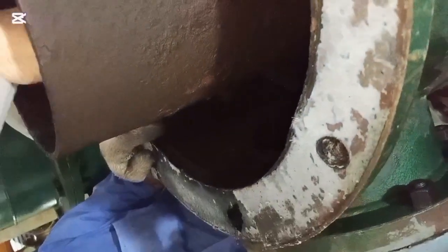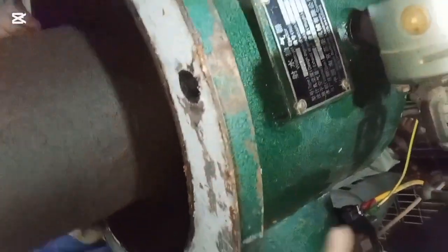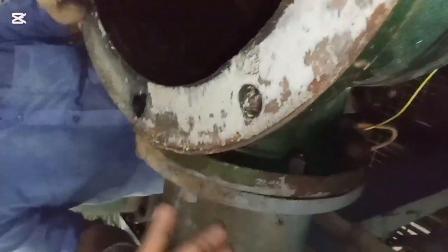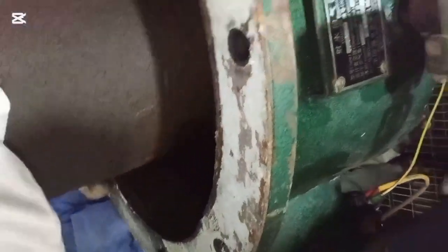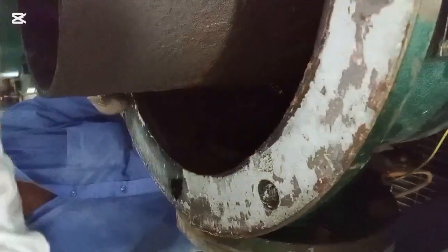A healthy sewage ejector pump runs quietly in the background. If it is heard grinding, rattling or humming, or you feel vibrations through the floor, that is a strong indicator of internal damage. The motor or impeller may be worn, loose or obstructed. So at that time we need to maintain the ejector.